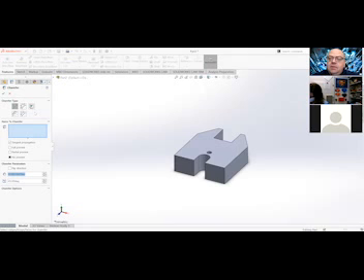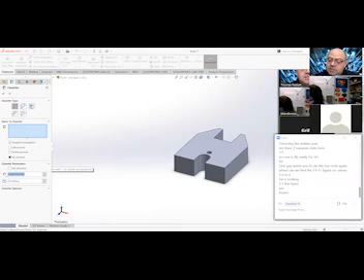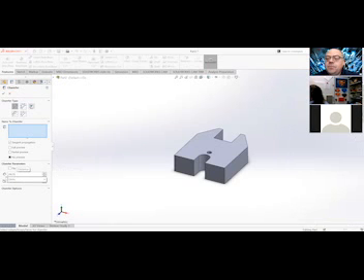That's going to bring up a new panel on the left side. We'll then leave all the settings the way they are except for the size. The default size is random. It just randomizes out. So I want you to change that size to 0.0625. Okay, that's 1/16 of an inch, 0.0625. And then we're going to pick certain edges. And it's going to give you a preview of what happens as we do this.